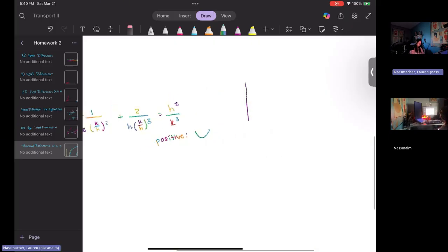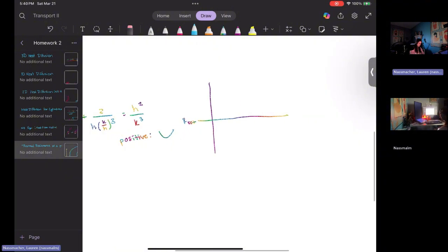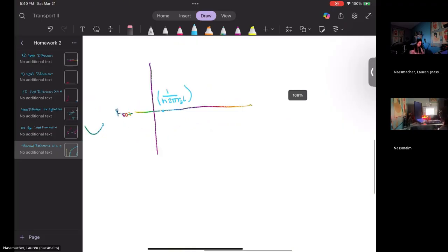Graphing this out, we'll say that this line is our total. And somewhere on this line, the very beginning, we have our base pipe, and that's a pipe without any insulation. That's going to be 1 over our thermal heat coefficient multiplied by the area, 2 pi r2 times the length.